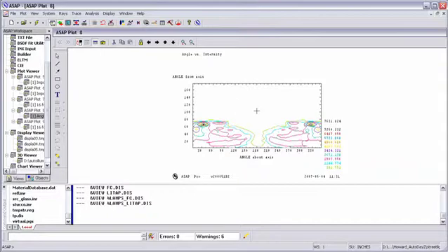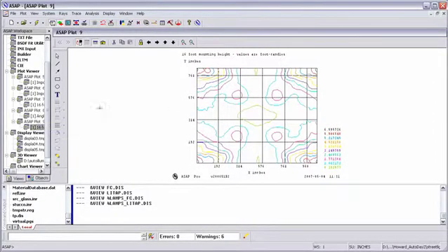And then we've got a plot of what we call the type C photometry of the lamp. For people that are familiar with that, this would be as though we'd photometered the lamp in the lab. And this particular lamp was designed to be a full cutoff lamp, and this plot is showing us that we do not have any light above, any uplight, and that we are meeting the full cutoff criteria. And then this is also an isocontour plot of 4 lamps positioned at each corner, so we can see the illuminance that we would have if we had used 4 of these lamps to light a roadway section.